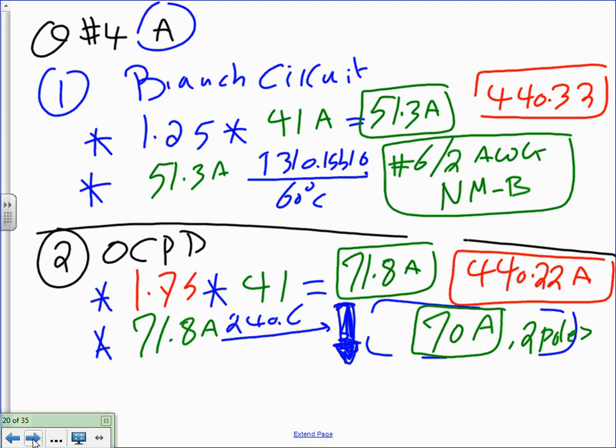Now, if it doesn't work, if you size it, you install it, and it doesn't work, then you go up. But we didn't size it, we didn't try it yet. Default 175. I used to default 225, but default 175. Guys, the lower the overcurrent device, the safer your system is. Everybody knows that. The lower, the safer.